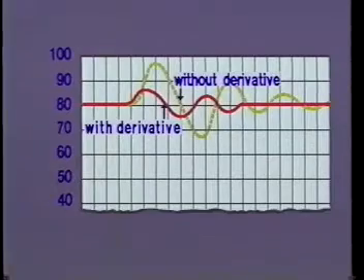The additional valve motion caused by the derivative or rate action unit is very good at reducing or eliminating overpeaking. The amount of rate action can be adjusted to suit the process in question. If the rate action is too fast, the process will become unstable. If it is too slow, the controller will be governed by proportional and integral response only and will cause overpeaking.